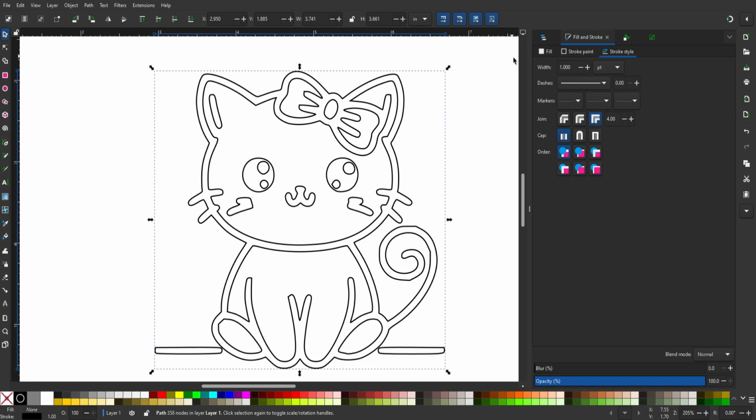Now, because you deleted the raster, you can fill in this area knowing that you can etch it or not. If you were confused with the other file, it wouldn't have worked because it was still just a raster image. You can etch raster because the way etching reads is, is it black, is it white, and then it goes across like a laser printer does. It goes back and forth across the material and just lasers when it senses a black pixel. So that's etching, and then cutting follows a vector.